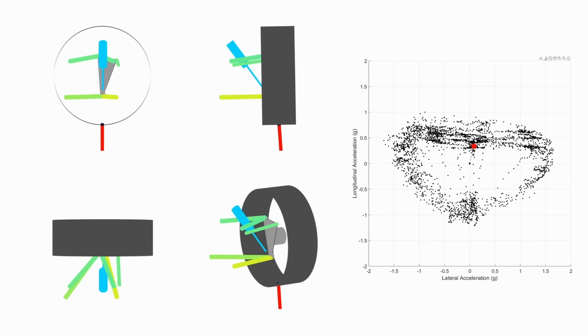And you probably noticed there's a couple of limitations with this. One of them is that all of the loads have been done with a static suspension system. I haven't put in the fact that the suspension is moving as it's going around corners and braking and so on. And this isn't as crazy as it sounds. We have actually had cases where we've done these calculations and put strain gauges on all of the links for a car, taken around a track, and seen pretty good validation between the calculations you see here and what the actual forces were from the real car.